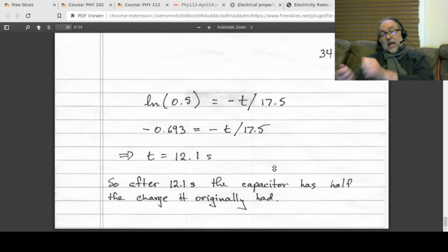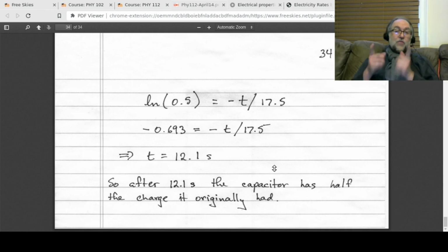And on the oscilloscope, you can actually have the settings so that it triggers on when it reaches that particular charge, and you would actually see that characteristic shape on the oscilloscope. Okay, now I should say something. Oscilloscopes technically only measure voltages, and so you wouldn't be measuring the charge on the capacitor, but you would be measuring the voltage drop across the capacitor, and the voltage drop across the capacitor and the capacitance will tell you what the charge is on the capacitor. Okay, so there it is.